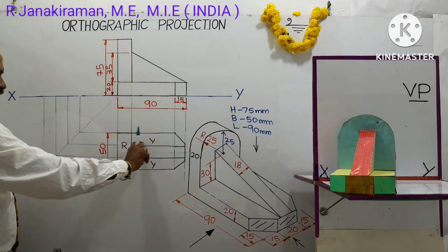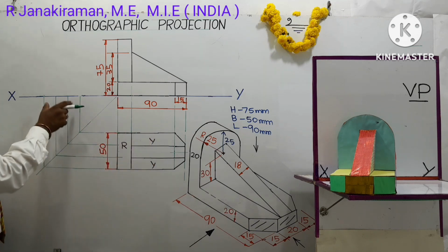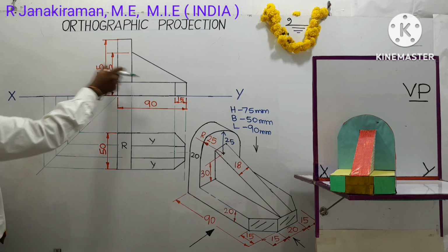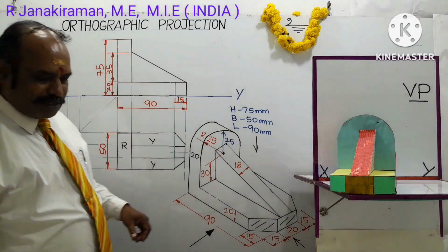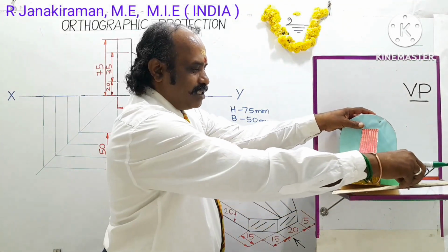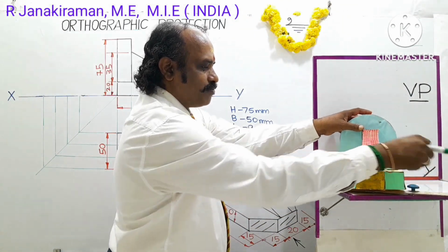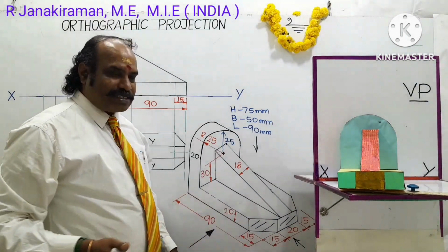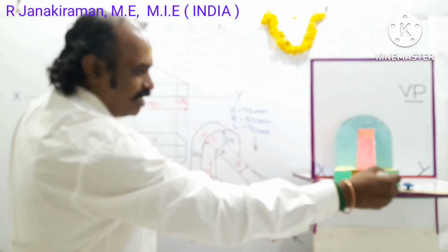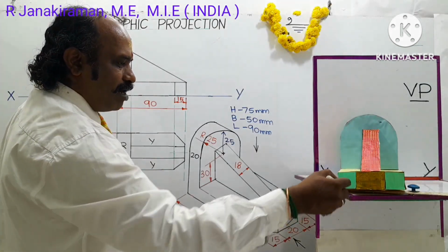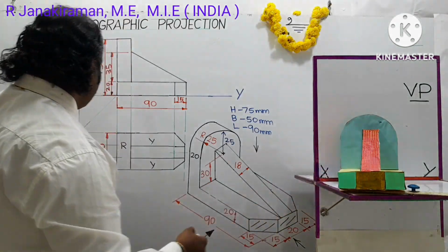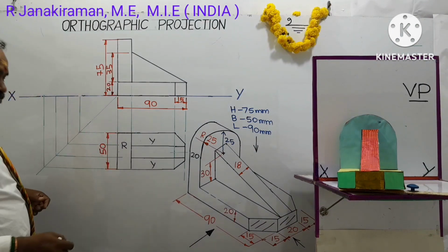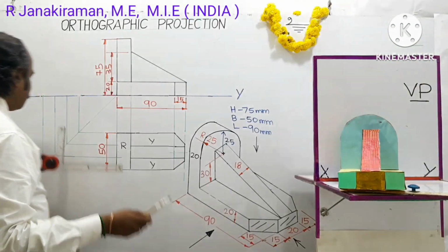What are the portions that is seen in the top view shall be traced to locate the side view, called right side view, which shall be drawn on the left side of the front view following first angle projection principle of the method. So this is a side view called the right side view. Base thickness is the same as 20 mm, uniform base thickness. This green on the right side, left side one green small portion is there, center gold color part. This 50 shall be traced like this. This also be same as 50 mm. Use HB pencil object line.